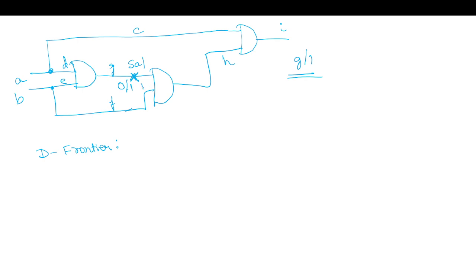So this is having a D bar value. So now G is at D bar. That means for this gate, if we say G1, G2, G3, in the J frontier, G1 is having a fixed output and don't care at the input. And in the D frontier, the G2 gate is having D as the input.